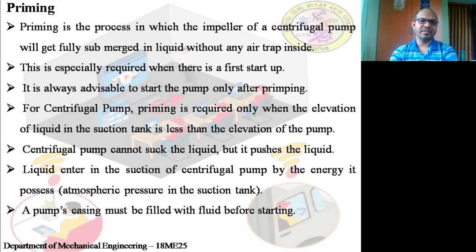This is especially required at the first startup. It is always advisable to start the pump only after priming. For a centrifugal pump, priming is required only when the elevation of liquid in the suction tank is less than the elevation of the pump.